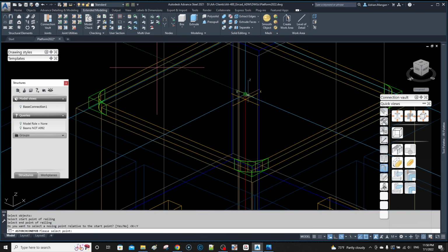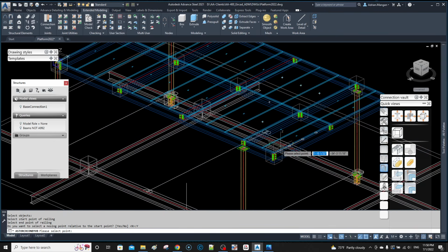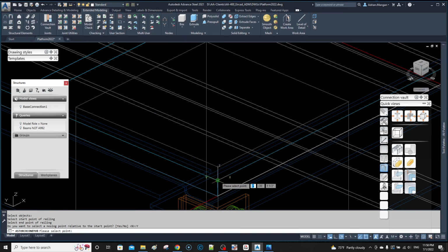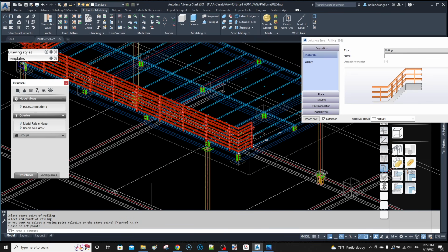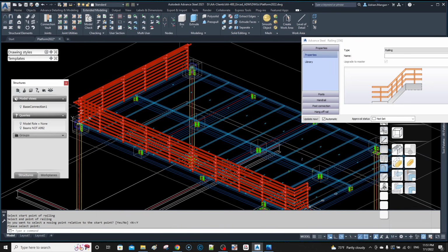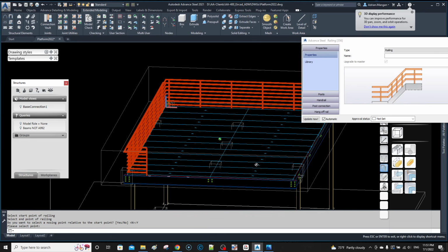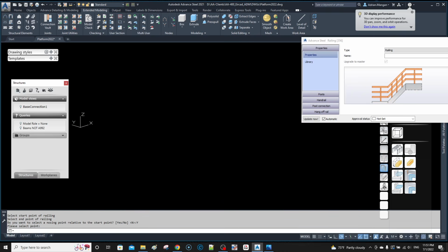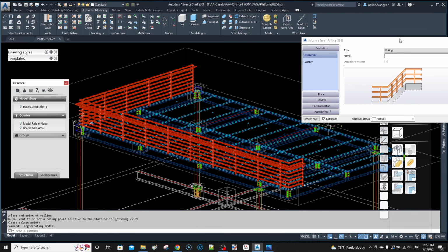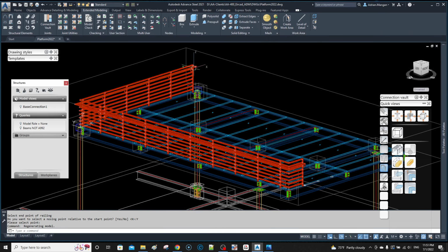So I'll say yes. And I'll say I want the nosing point to be the top of the grading, which is up 1.5 inches. Now I know I'm going to end up doing something wrong here when I'm doing this handrail, but let's have a look at it. It's come in with a weird handrail that I did on another job. You can see it's actually coming pretty good on those 3 railings. It's almost worth trying to see if it'll go the whole way around. Generally it doesn't, but let's see what happens.